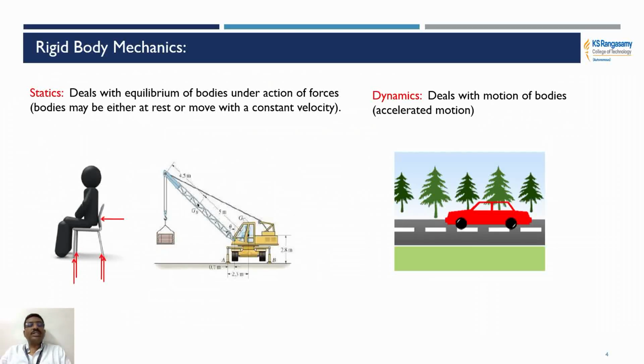So statics is the study of bodies which are at rest. It deals with the equilibrium of the body under the action of force, and the bodies may be either at rest or moving with a constant velocity. If you consider the body given in this figure, the body is seated on a chair. Here the resisting forces, the external forces and the self-weight of the body are considered for the equilibrium of the particles. The equilibrium conditions are summation of horizontal force equal to 0, summation of vertical force equal to 0 and moments equal to 0.